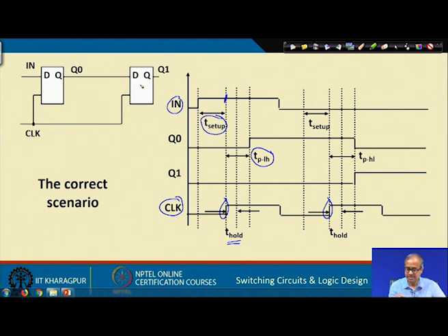Considering the second flip flop will be taking this Q0 as input and storing it there. So, this new value of Q0 at the next clock will be coming to the D input of the second flip flop. For the second flip flop, again you see the setup time constraint is satisfied, because Q0 is available here only. So, there is sufficient buffer here, and of course, hold is also there. So, after that time Q1 will go from low to high. So, it is TPHL, and after this delay, this Q1 value will get stored here, right.